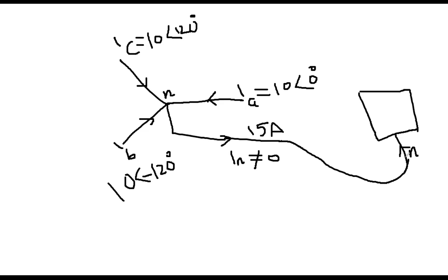And then, for example, at some point they are grounded. Like this three-phase system and that one were grounded at some point. This was the neutral line of this system. And there was no issue with this system initially. There was an issue only with this system, which is unbalanced. Consequently, current was flowing and that current will enter the other device.